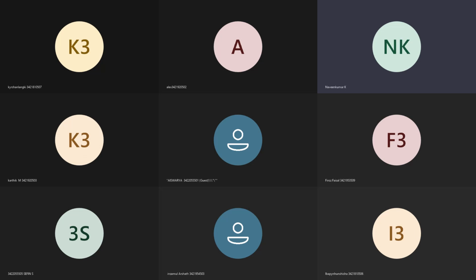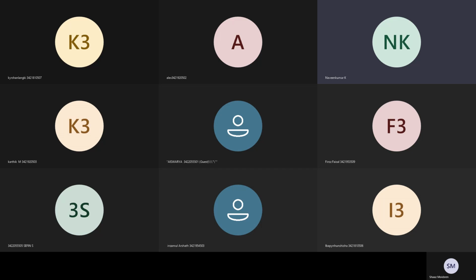While the second difference, while you construct any type of structure, whether it may be residential or industrial, with reinforced cement concrete, you follow a sequence of construction. First you will have the shuttering process. After that, you will place the reinforcement. After that, you will pour the concrete. Okay, this is the way you do the construction. After setting of concrete, you will demold the shuttering. Okay, so this is the sequence of work you follow conventionally.